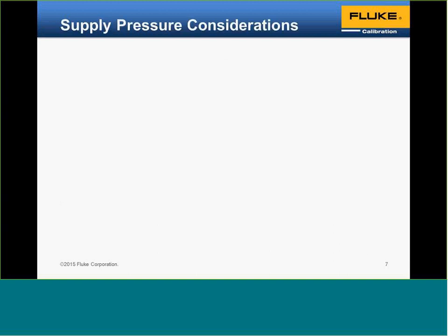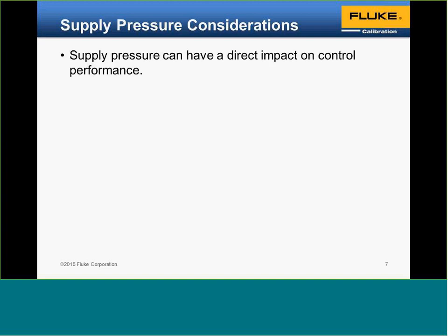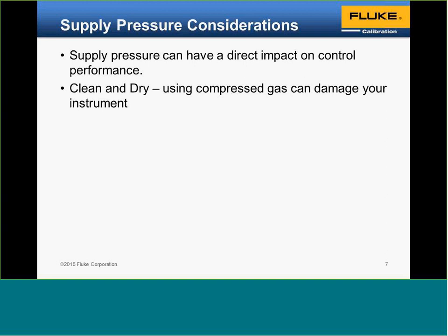So let's start with supply pressure. That is the pressure coming into the instrument that the controller is then metering to a controlled test pressure. This can have a direct impact on control performance. First, make sure they're using clean, dry gas in the pneumatic controllers.